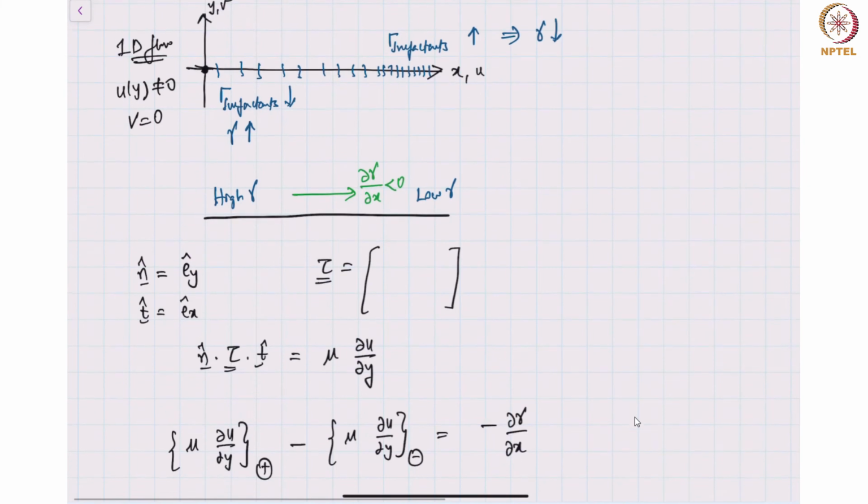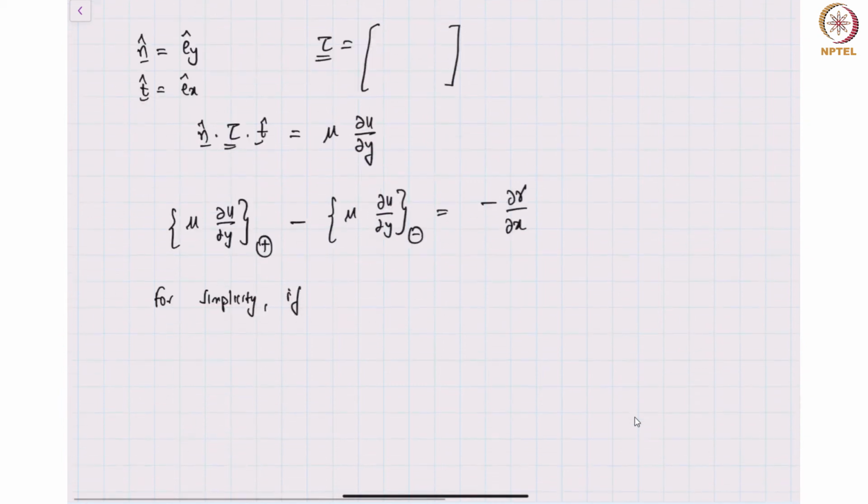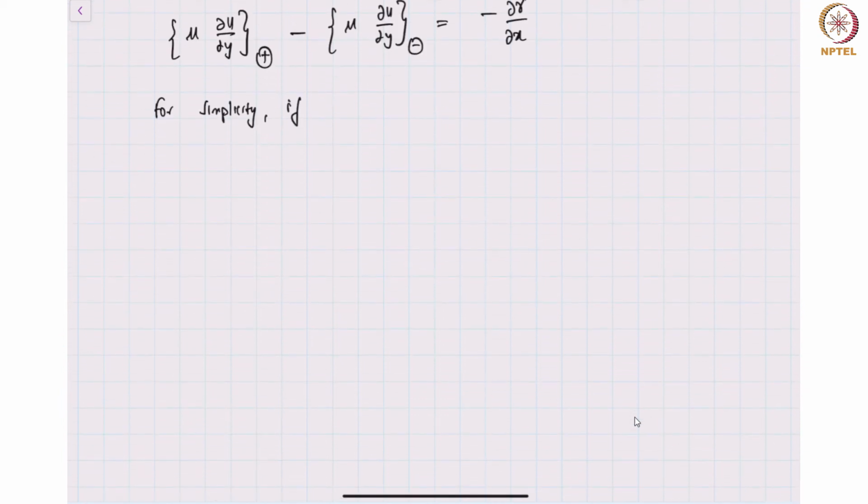This is not the only way to get variable surface tension. I could apply heat on one side and keep the other side either at room temperature or cold. At higher temperature, surface tension would reduce, so I apply some heat on the right side and less heat on the left side, or maybe even keep it at room temperature. Automatically you will get a temperature gradient, and therefore a surface tension gradient.